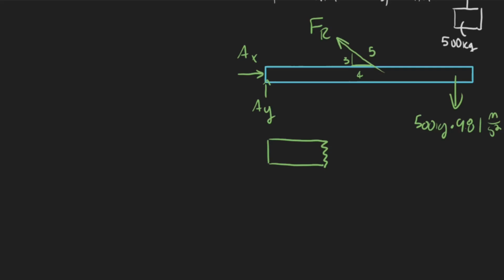Okay. Now I know that this section of the beam has to be in equilibrium, which means that this force AY and this force AX has to balance with some force being carried inside the other side of this beam right here onto this one. So I know that there has to be some force basically that would push back like this. And then there could also be some force pushing back here, and there could even be a moment because this side right here essentially has to be fixed if the whole thing's in equilibrium.